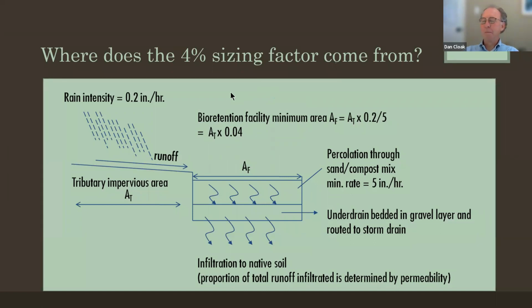I'll back up a little bit to say those criteria that are being referenced. One, the most commonly used one at the time that it was written was to design settling basins. And it's still in all the permits. That's where that whole idea of water quality volume came from. You had to capture this water quality volume and hold it quiescently for 24 or 48 hours and let the pollutants settle out.